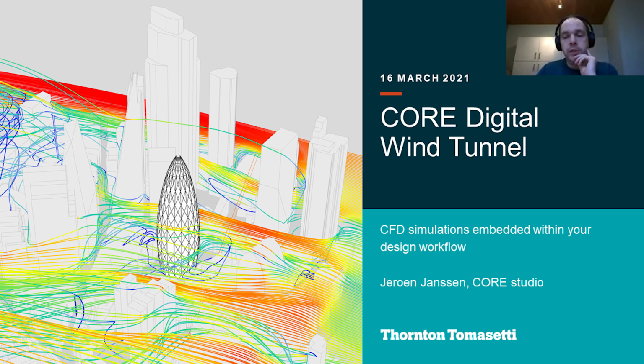Pedestrian comfort, that's more and more accepted already, and also the City of London, interestingly, for the very tall buildings over 100 meter, let's say, you'll actually have to do both. You already have to do the physical test and CFD for pedestrian comfort. So I think things are changing, but slowly, let's say.